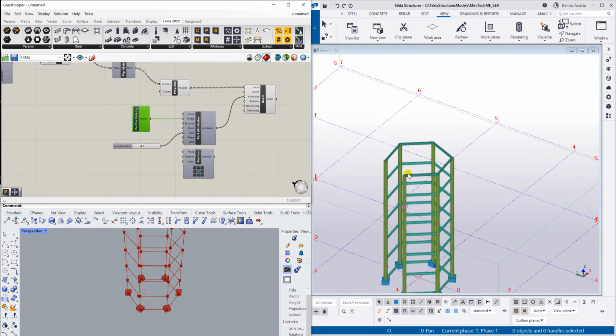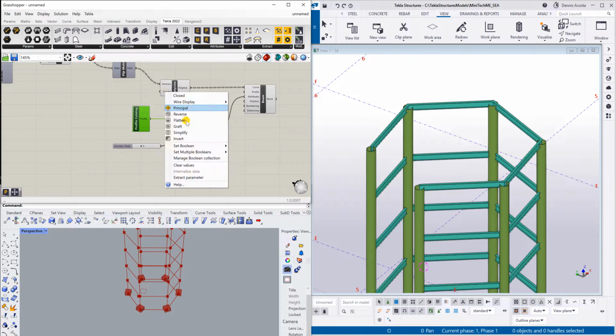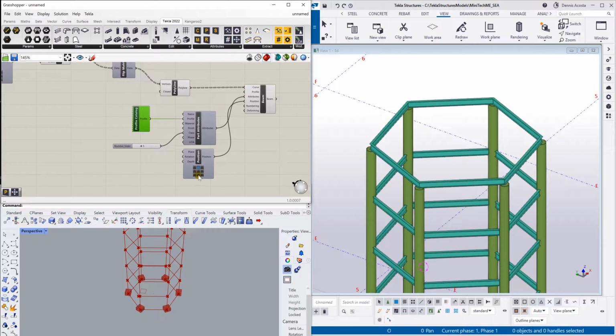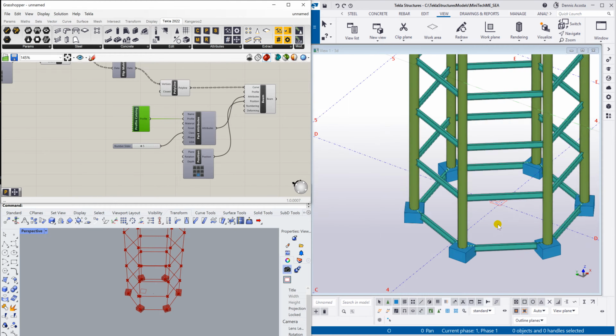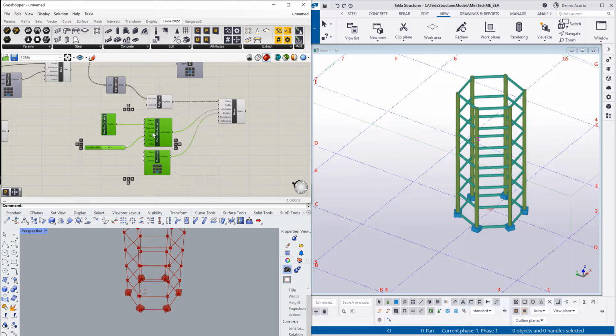See, I have the attributes, I have the beam. Now to close this polyline, you just go to this close, right click, and then here under the set Boolean, you set this one as true, and there you go. So it becomes closed. And then here you can just simply change the position. Position here. There you go. Oops, behind. There you go. Okay, so we have now the beam.